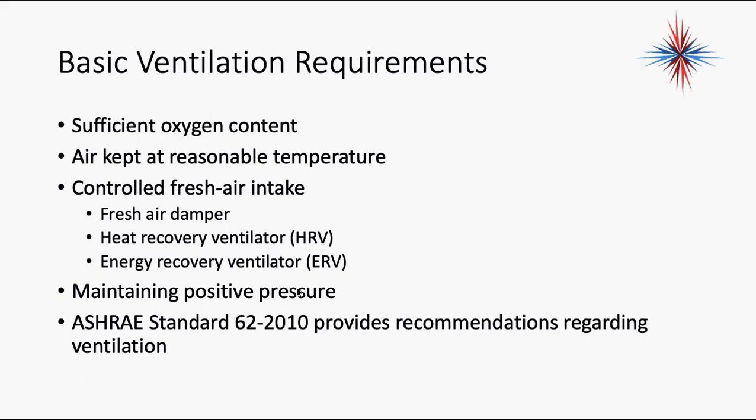If you walk into a building, any building, any place, and you pull a door open, if that door opens and you can feel the air coming out of the building, just sort of like a slight breeze as you open that door, that building is being maintained in a positive pressure, which means the outdoor contaminants are not going to be pulled into that building and all the exhaust is working properly.